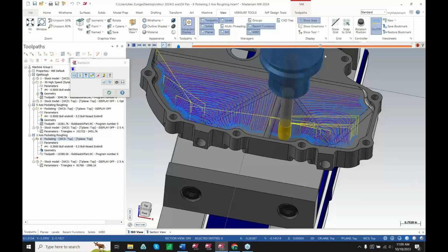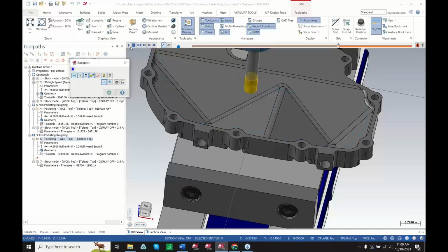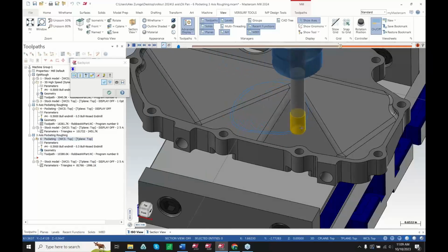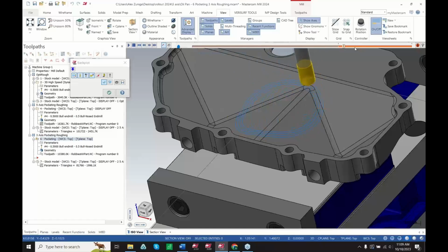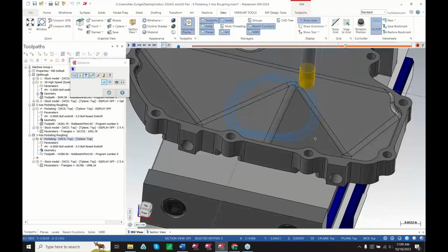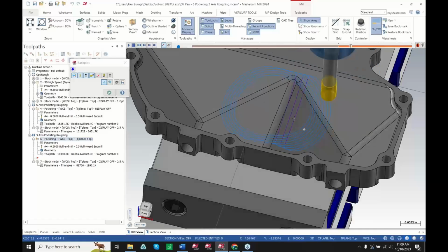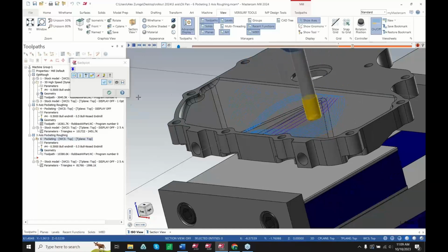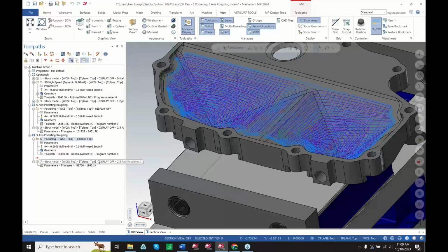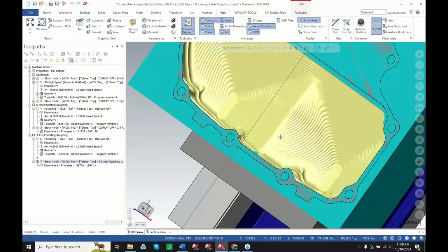So if I get down to this bottom portion here and trim it out, you can see here we're walking normal to the face from a 3-axis thought process. So this is kind of cleaning it out, just as almost as good as what it was if it was walking perfectly normal to every single face. This is walking in. And the result you have is something like this.